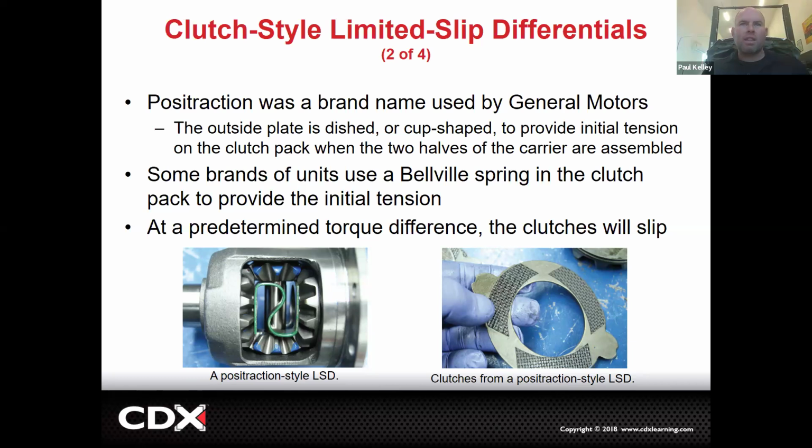On the Aztec, they had an issue with the clutch pack. It wasn't exactly a differential. It was actually an all-wheel drive, and it had the viscous clutch, but they had clutch discs. And a lot of times the incorrect lubricant was used, or it would have debris or whatever. But when you'd go around turns, the clutches would try to grab and it would shudder. Okay. So the fix was drain that fluid, put the correct fluid in, and then go drive it in 30 left-hand loops, 30 right-hand loops, and then 30 figure eights.